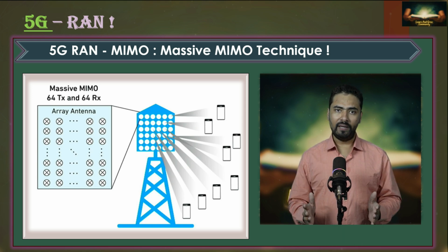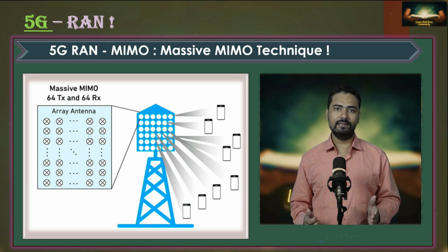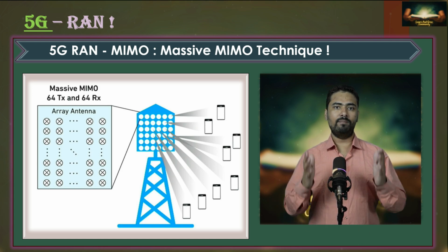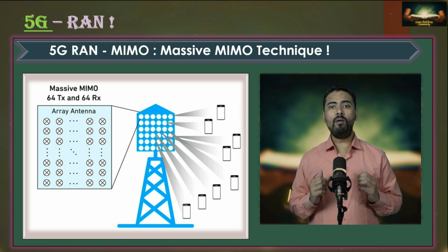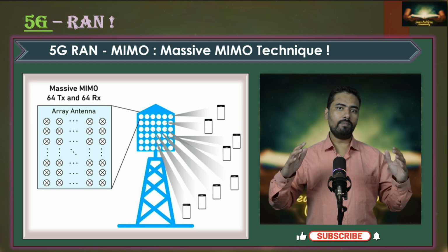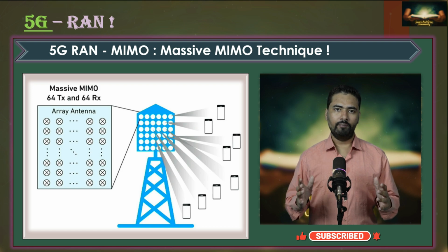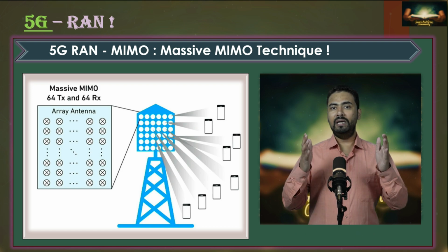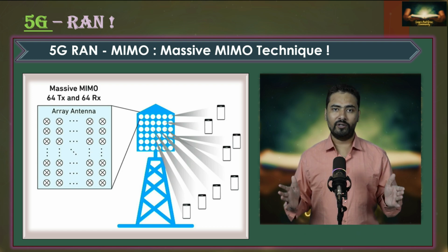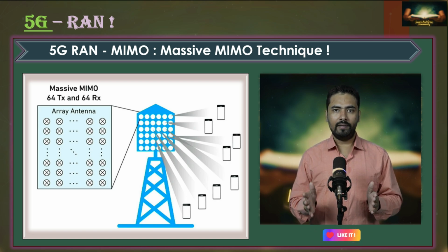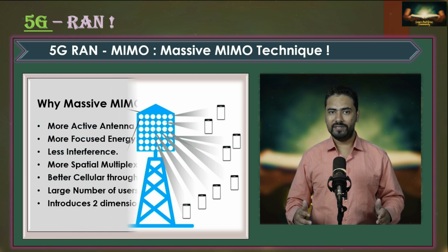In beamforming, the phase of the transmitting signals is adjusted in such a way that it adds power in some specific direction to form a beam and cancels power in the other directions. So that was one thing. But we also consider that millimeter waves have poor propagation characteristics. So for millimeter frequency bands, beamforming is important to serve 5G users.